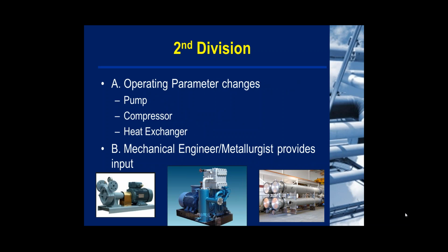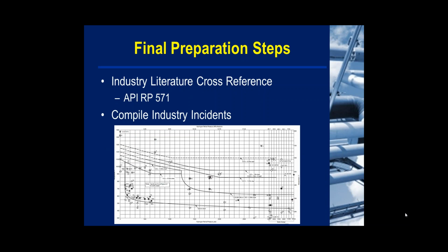Facilitators normally call generating nodes more of an art form, and they have more flexible boundary rules, like establishing a single node for every single process chemical, or different phase changes, applying the boundaries at inlet and outlet of major equipment. For example, we see just a quick PFD there. The shell and tube have different nodes there, and the inlet and outlet of different major pieces of equipment are used as node boundaries.